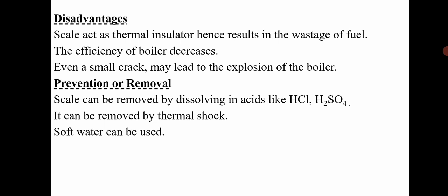So this scale acts as a thermal insulator which reduces the efficiency of the boiler, and also it causes waste of fuel. It increases the crack formation, which leads to the explosion of the boiler. So scale formation can be prevented with the help of acids like hydrochloric acid and H2SO4. It can be removed by thermal shock, and also when we use soft water, we can reduce the formation